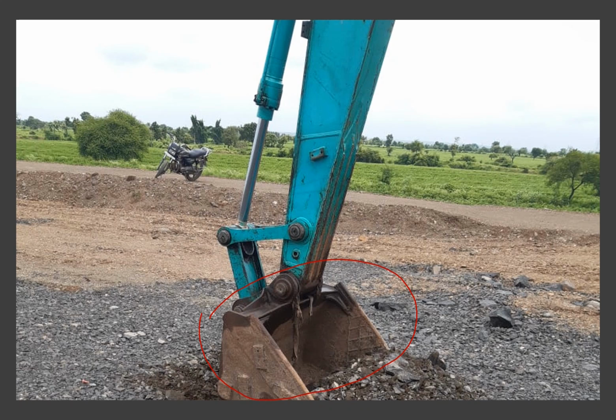So this will help you to collect the samples at a defined location for a set size, say 1 meter by 1 meter, to the required depth where the construction of the rock fill embankment is being done, and then take out the material and check for the size of the material which is required to be followed, and then the minimum percentage fines required to be followed.